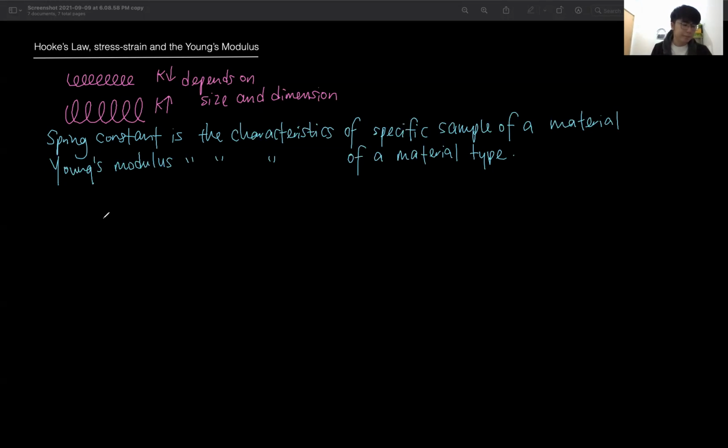Now, Young modulus of steel. Here are a few examples of the values for the common ones: steel, plastic, rubber. Usually, Young modulus is very huge. The value is very huge. It has the same unit as pressure. So steel is about 210 gigapascal. Later we'll come to what Young's modulus actually is, just to give you an idea here. It is a measure of what? Stiffness.